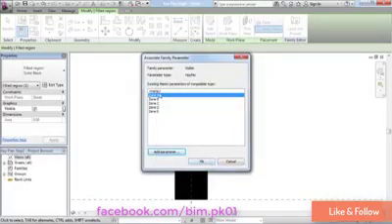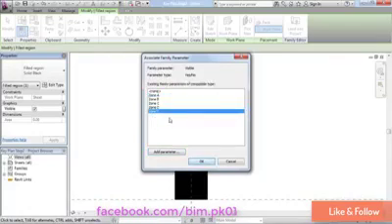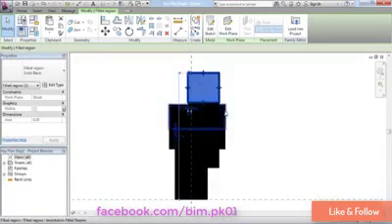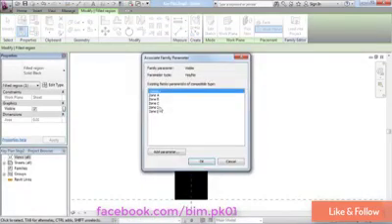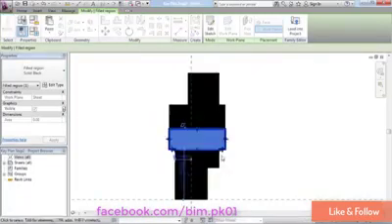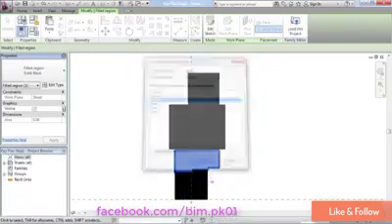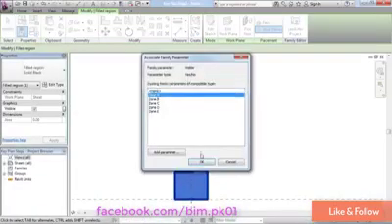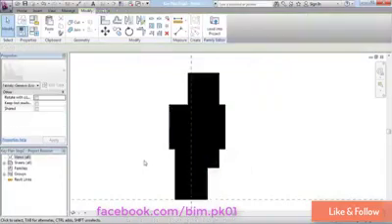And once you've created the last one, you just want to make sure that Zone E is selected before you click OK. We've created all 5 in this dialog, but we want Zone E to be associated with this filled region. And then we simply want to select the others and associate them with an appropriate zone. So that one's D, this one's C, B, and A. So that gets all our regions set up. It associates a parameter with all of them. And in the next movie, what we'll do is begin creating family types and formulas to actually control which zone is turned on under which circumstance.